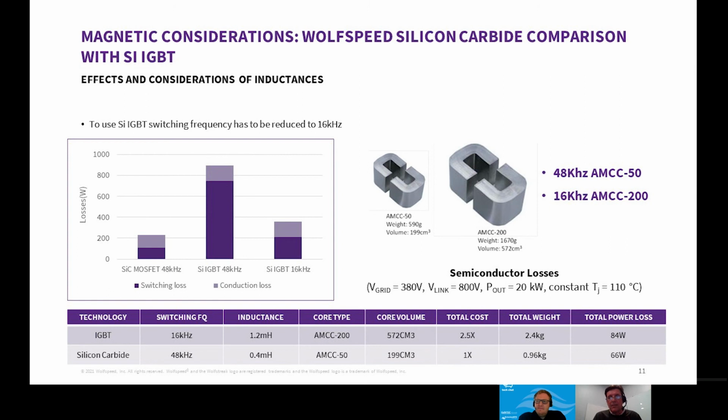Soft switching, again, 3 times that switching frequency of silicon. Whether if you're 100 kilohertz for silicon, you could be 400 kilohertz for silicon carbide. And again, that isolation capacitor and the input and the filters, boost inductors, the inductor and the magnetics come down considerably.